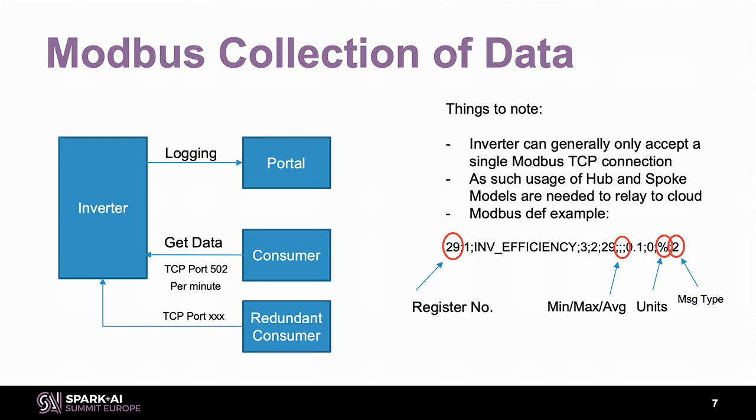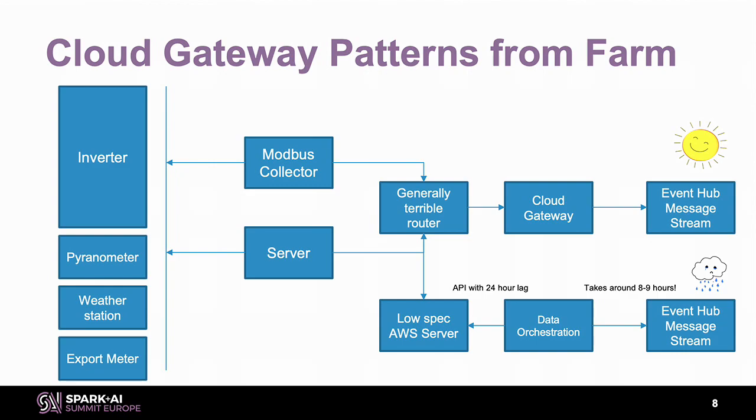And then with this definition we get our metrics, lots of them. So with inverters, with something called pyranometers, which take in the energy from the sun and give us a measure, so what does that solar irradiance look like? What are the PV cells actually taking in? Then generally you have an on-site weather station. It's not great. It's never going to be as good as Met Office data, but it is on-site. And you'll find that generally the weather providers collect weather data from tens of thousands of weather stations, but they're dispersed, so you have to effectively triangulate to see where the solar farm fits within all of these weather stations. And then you have an export meter as well. The export meter is the last point where the energy gets put onto the grid. At each point where it goes through the farm, you end up with losses because that's the nature of electricity. So we want to understand what gets put onto the grid.